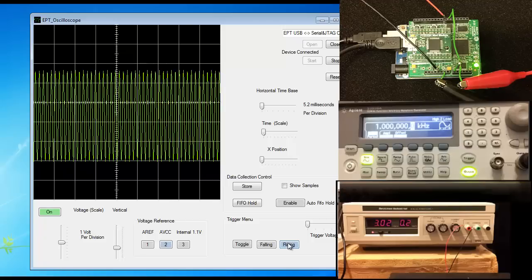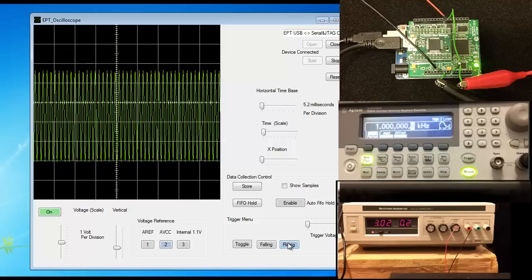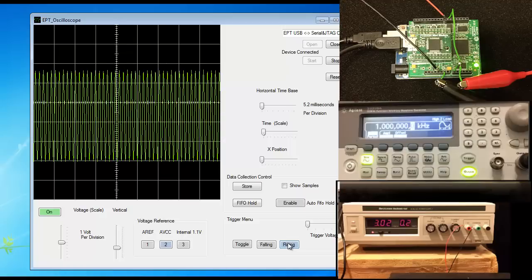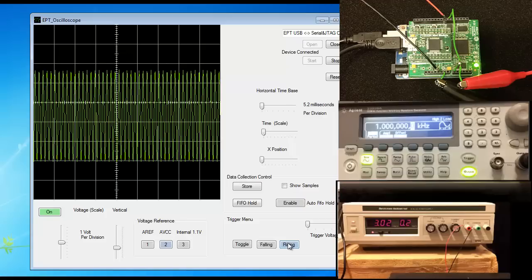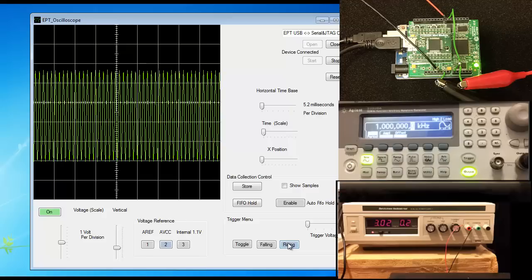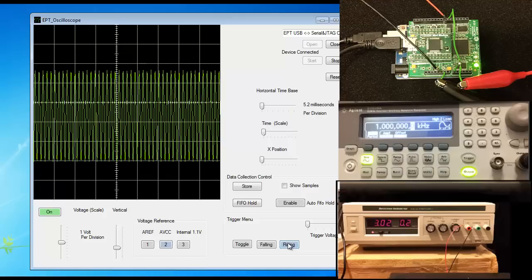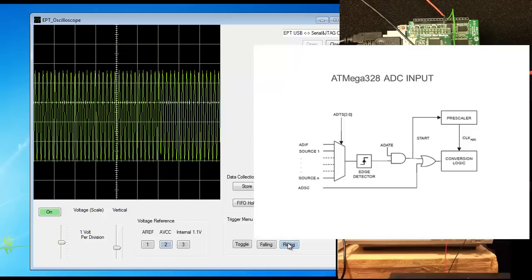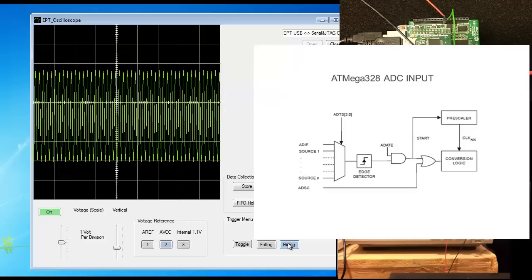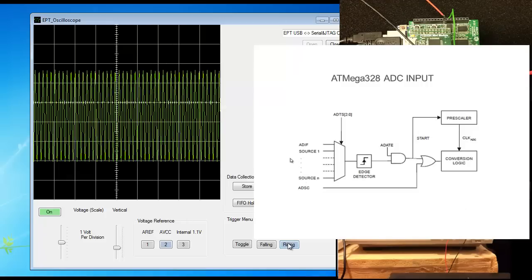The fast Arduino scope does have its limitations. It is most notably limited by the ATmega 328 microcontroller. The chip uses an ADC, which we select the 8-bit mode to increase the throughput speed. In the block diagram of the internal ADC circuit of the 328 microcontroller, we can see the circuit functionality.